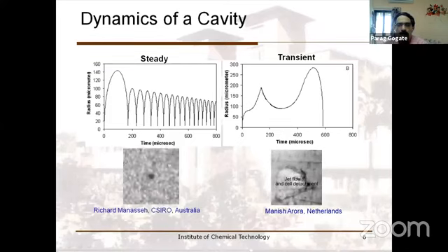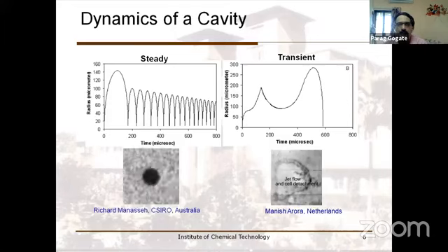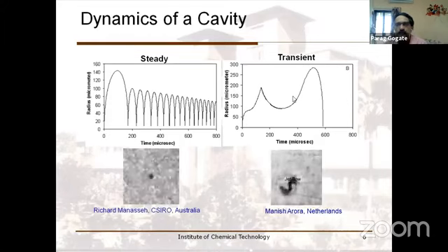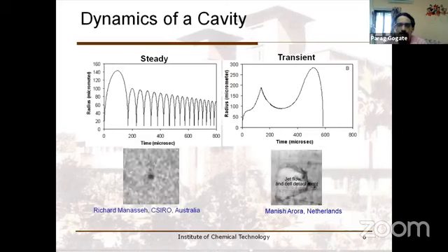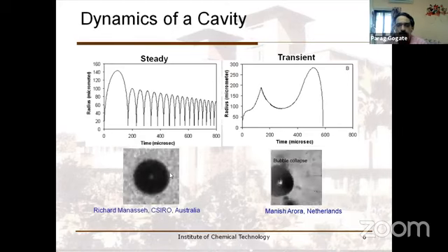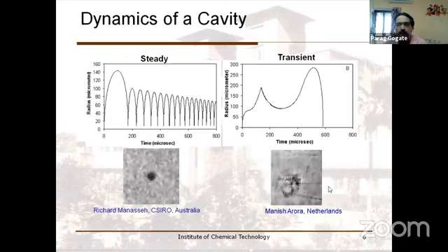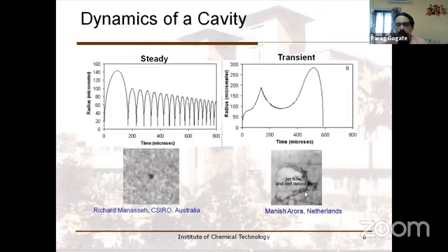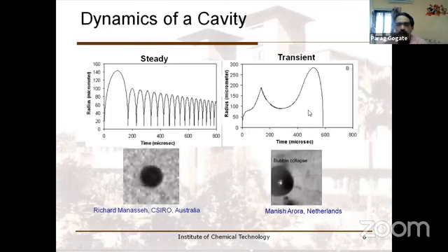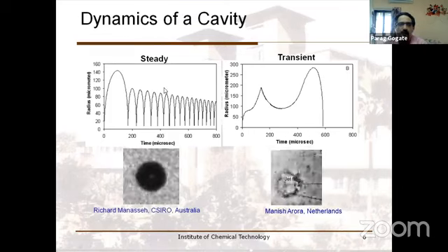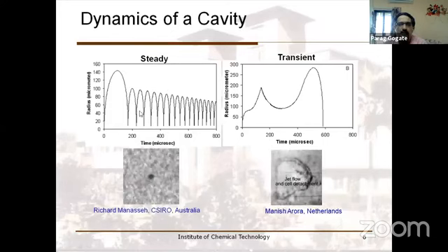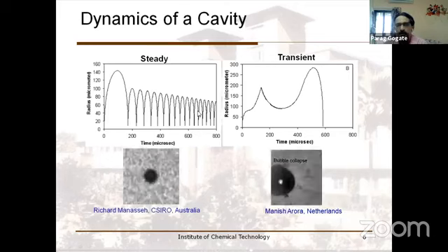Now, what will be different is the cavitational intensity, which is going to be generated in steady cavitation or in the case of transient cavitation. In the case of transient cavitation, it's going to be much more intense. And you can clearly see in this video as well that the bubble collapse is introducing jet flow, and then some amount of solid dispersion can happen in the case of transient cavitation. In the case of steady cavitation, there is no such effect. You are just getting intermediate pressure pulses.